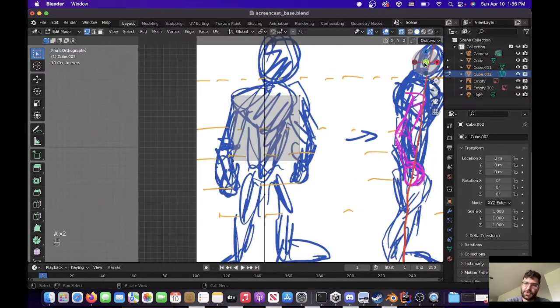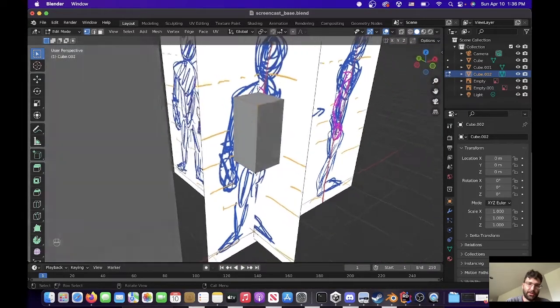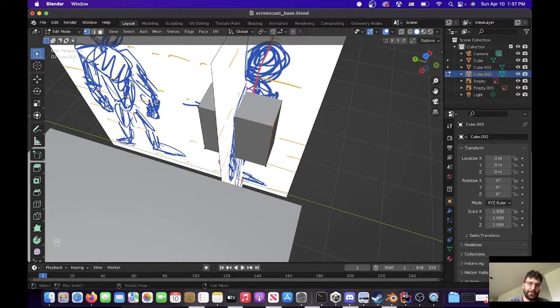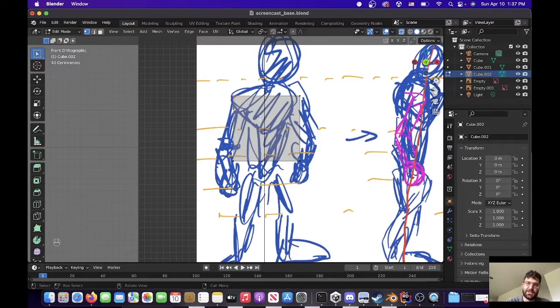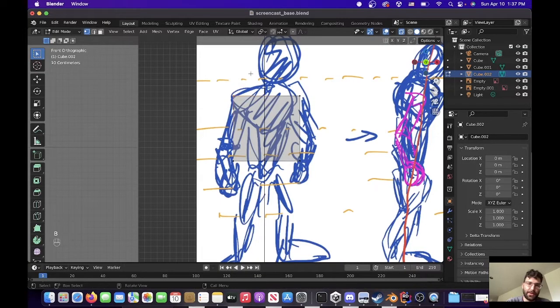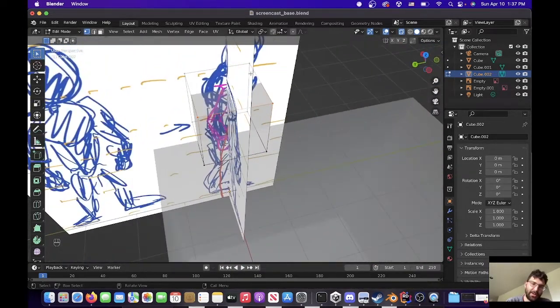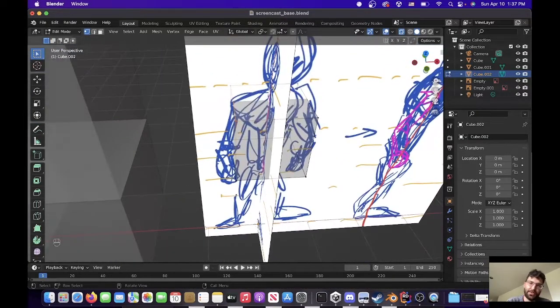If I am straight on and this box isn't selected and I orbit, I only selected one vertex. If it is on, that's X-ray selection. See, now I can see all the other points. If I do the same box select operation, everything that intersects the viewing plane is now selected. In this case, that's what we want. You don't always want that.